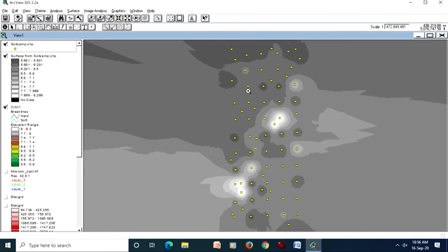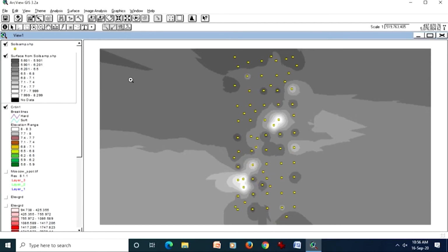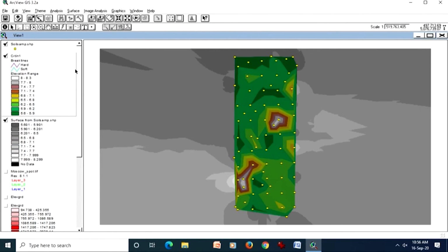But because you know that a raster can only be stored in two shapes, either rectangular or square, this current one is definitely in rectangular shape. If I now display my TIN over it, what I am seeing is that the TIN was restricted only to wherever I had the points, because in a TIN there is no concept of extrapolation, not at all.